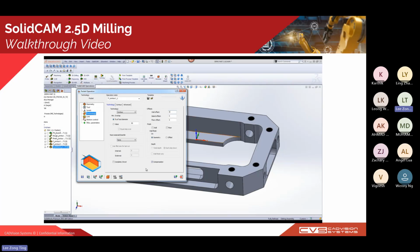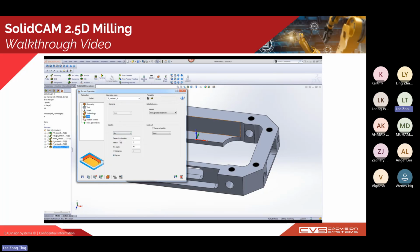because I want to do a finishing. And with this option right here, you can choose to only machine the rest material left by the previous operation. After I choose this operation, you can see that I can specify the previous operations. Previously I used a 12mm, so I will type in a 13mm end mill I'm going to use. After I do those lead in and lead out, those linking strategies, you will see the simulation in a while.